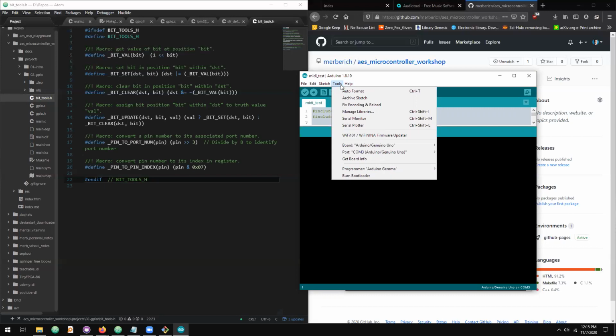So when you plug your Arduino into your computer, is your power LED on? That should be a green LED on the right-hand side of your Arduino. It is on. I'm wondering if your Mac just has USB permissions for serial turned off.